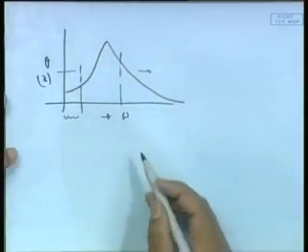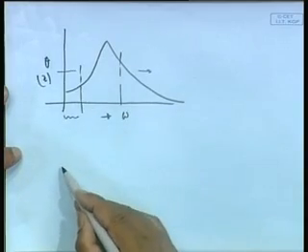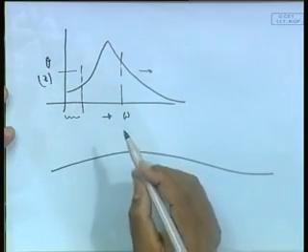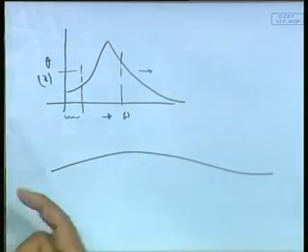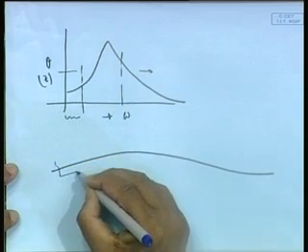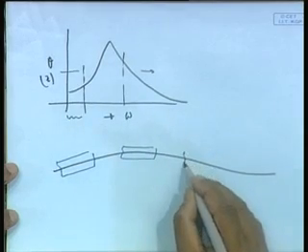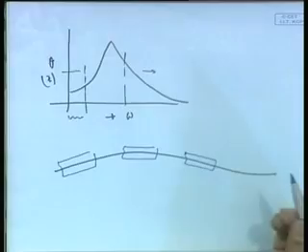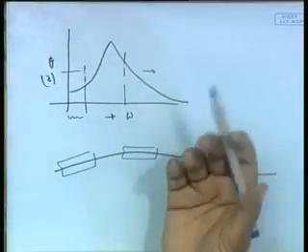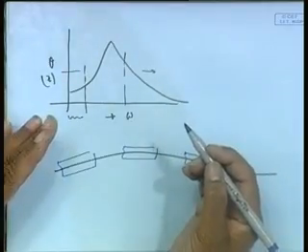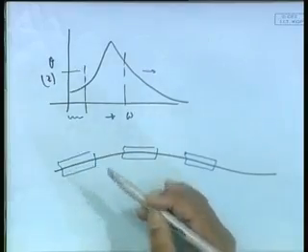Let's look at the pitch, how it looks in this case. See, a low frequency wave is like that. If you look at that, you will find out that the pitch is exactly in phase with this. That means it is always aligning itself like that. The low frequency part, one can show, will be in phase with the exciting moment. The exciting moment is actually in phase with the slope. That makes sense, and I do not have to go through the maths to tell you; we can always use our own logic to find out.